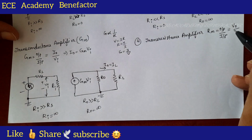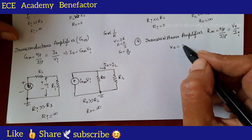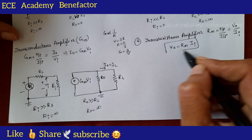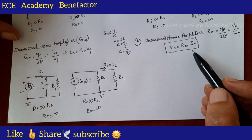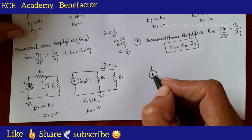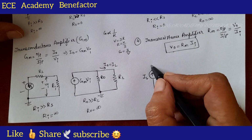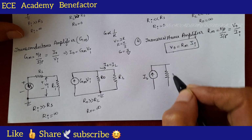Input is current Ii. So, what is the V0 value? Rm times Ii. So, at the output side we need to place a voltage source. At the input side we need to place a current source. So, place a current generator here, current source Is. With a current source Is, there will be a parallel resistor Rs.